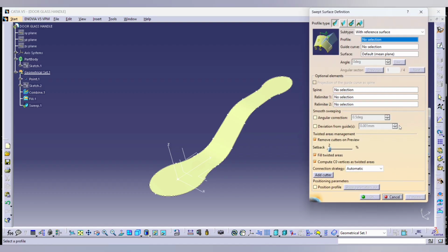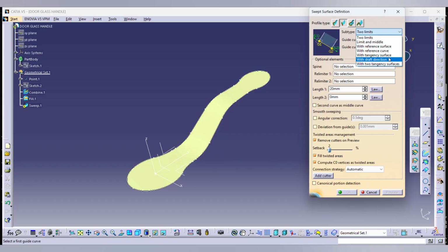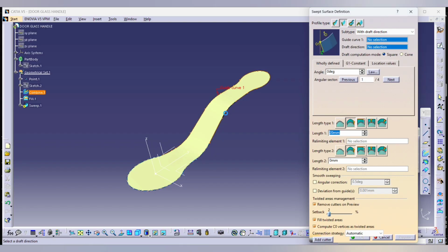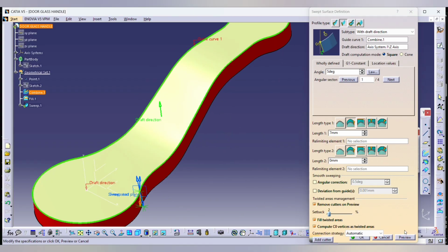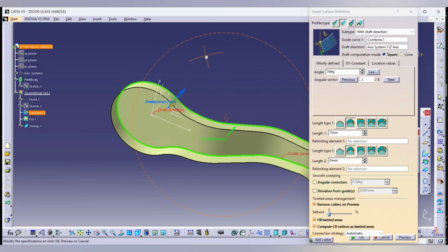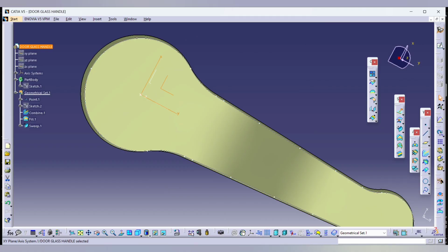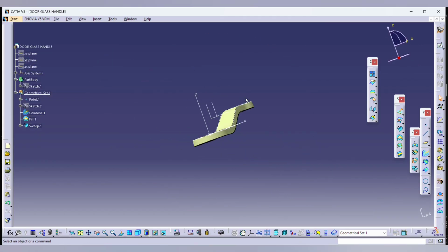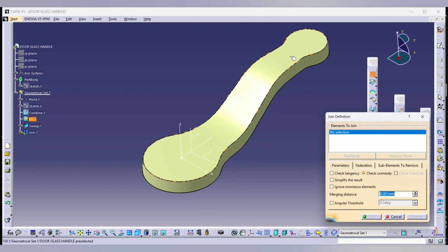Now further we'll do the designing. So by using the draft direction, select the line, edge direction 7 mm. We have to add the draft 5 degree, give the appropriate direction, and here you can see the proper draft as per our requirement has resulted. So we'll see the draft here. So we'll join both of the two.